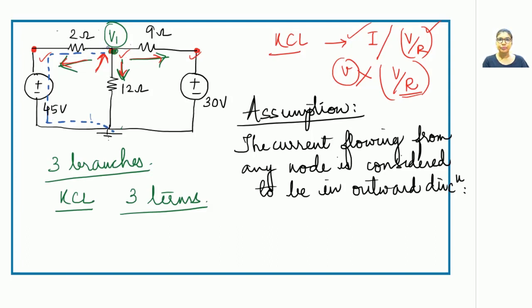Now this is V1. V1 is a voltage term. Now it goes in the left hand direction. Do you encounter any other voltage sources present along this path? Yes, there is one. That is the 45 volt source. So when you are traveling from V1 towards the ground, you encounter this 45 volts. Now upon encountering, what is the last sign of the voltage source that you encounter? You are traveling from V1 in the downward direction. So what is the last sign that you encounter? It is minus.